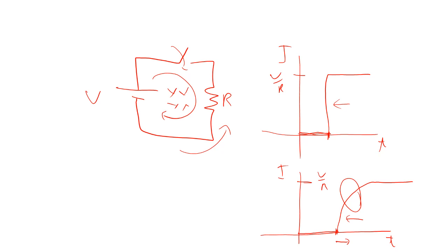Every circuit is going to have a response time when you turn it on or off, because there's always a little bit of inductance, so circuits never instantaneously become whatever you wanted them to become. How much response time depends highly on the inductance, because the time constant is related to the inductance of the circuit divided by the resistance in the circuit.